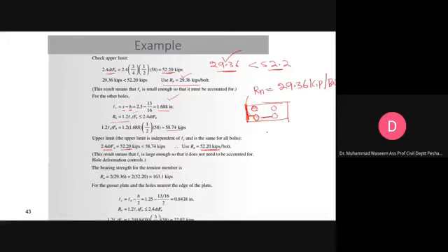we also have to evaluate the Rn, bearing strength. This comes out to be 52.20 kips per bolt. Now this is done. We have evaluated the bearing strength. We have checked the minimum edge distances. Now the same procedure we have to use. The total bearing strength of the tension member is two, these two bolts,